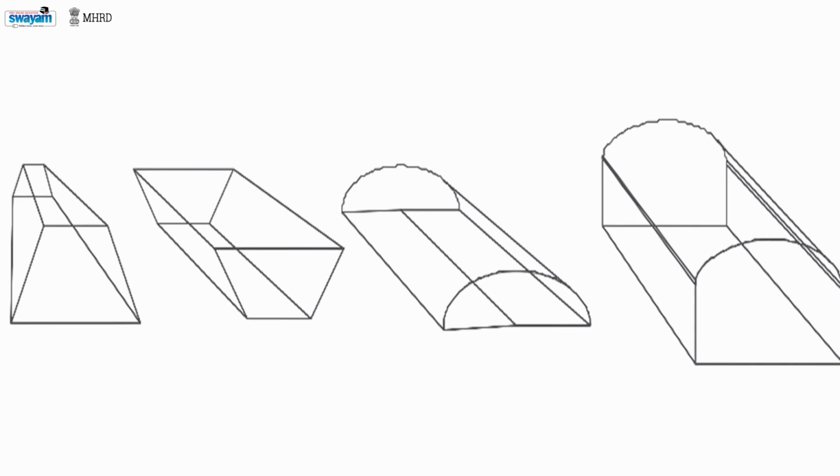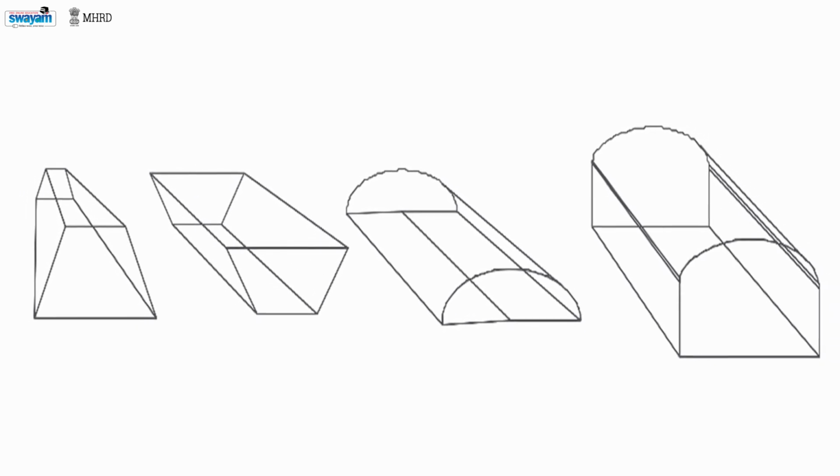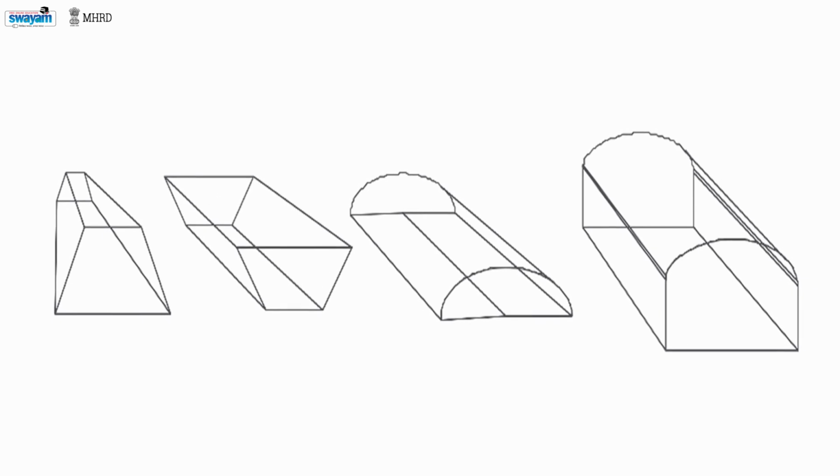The horizontal silo is the type of silo most often used to store co-ferments. The silo is constructed at ground level on fixed ground with walls on three sides. The material is fed horizontally, compressed and tightened with a special foil. The bottom layer of the foil is a thin cling foil which is stuck by remaining aspiration of the ferment. That layer is covered with thick black or white cover sheeting with webs to avoid damage by birds. It is weighed down with wires or sandbags.